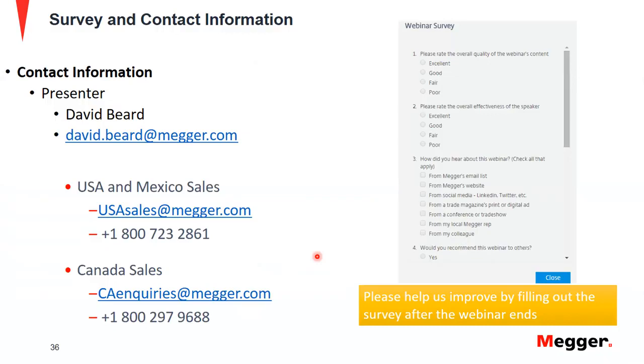Our first question is directed to Sugosh. Instantaneous is never really instantaneous. Can we calculate the magnitude of this instantaneous time? Yes, it is possible to determine this instantaneous time. The easiest way to do this is by running a timing test on the instantaneous function. You could have two stages in the test set, wherein you create a pre-fault state and then switch to a fault state that injects the instantaneous value, and then the relay trips for the instantaneous time.